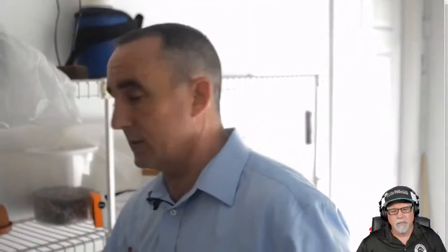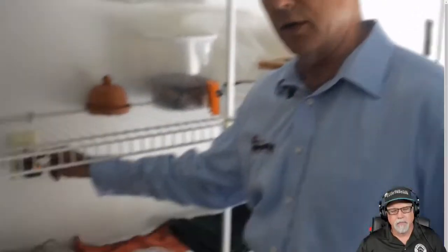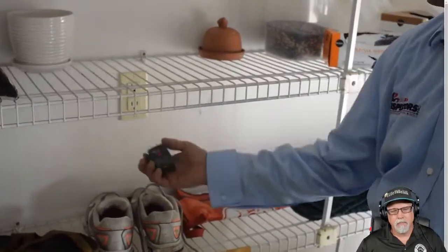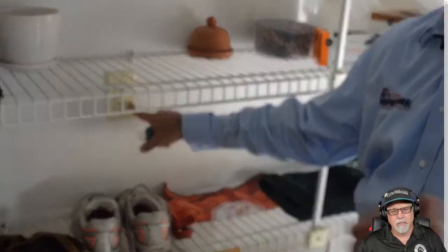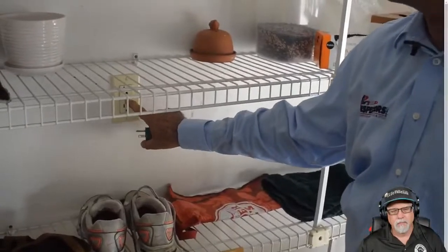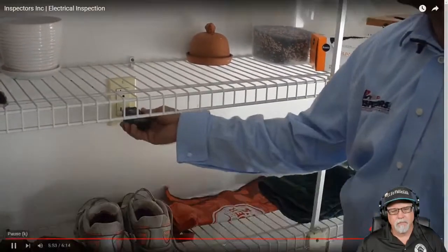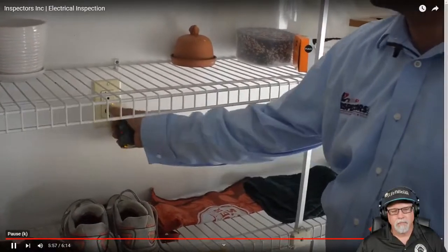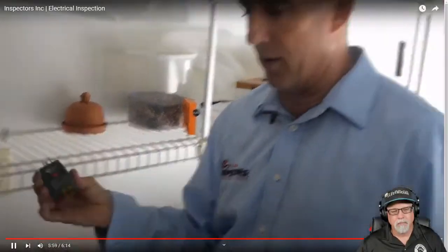Now the other neat thing is when you press the button over here, you can see that it will check for GFI. And there it is. This is a GFI outlet in a garage. It's wired to a couple of other outlets as well. And it has the reset button in there. And it did trip when it was tested. That means it is functioning properly. So it is supposed to shut the power off when we add a ground fault to it.